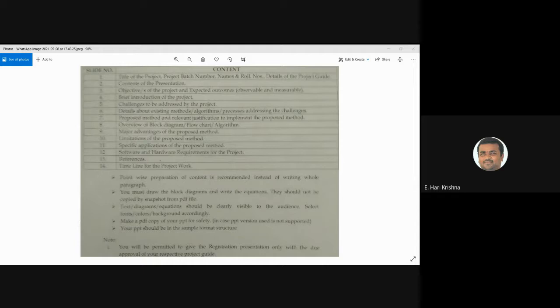in-band noise. That is, both signal and noise are in the same frequency band. Then we call that scenario in-band noise. I discussed this issue another time with Rahul while taking the problem of band pass filter and low pass filter discussion. So classical low pass, band pass, high pass, band reject filters will fail to eliminate the in-band noise.